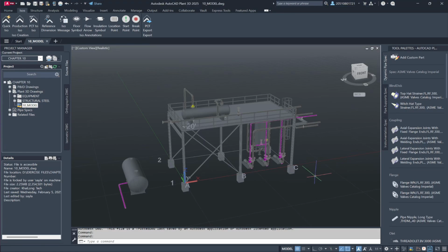A key benefit of utilizing automated isometric drawings is ensuring consistency. The efficiency and cost-effectiveness gained from automation would be significantly reduced if each issued isometric drawing required manual adjustments. To prevent this, users can embed standard annotations such as floor penetrations, directional arrows, insulation indicators, and notes directly into the model. This ensures that every time an isometric drawing is generated, these details remain intact.